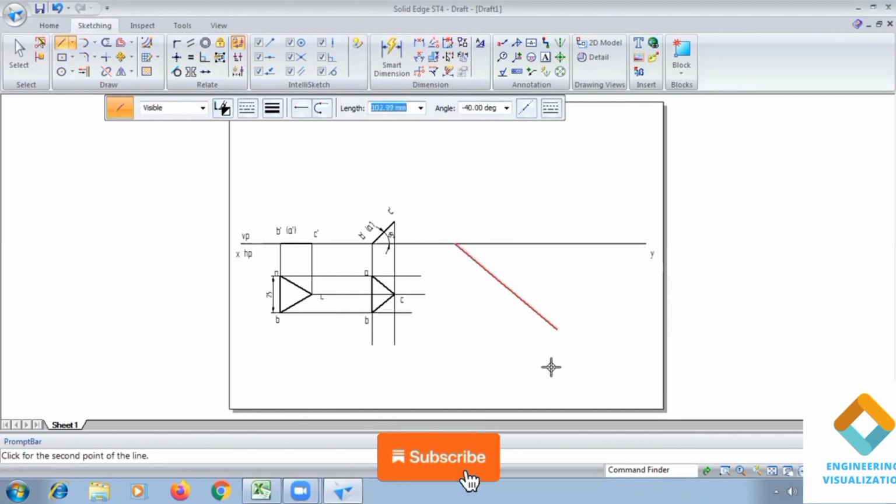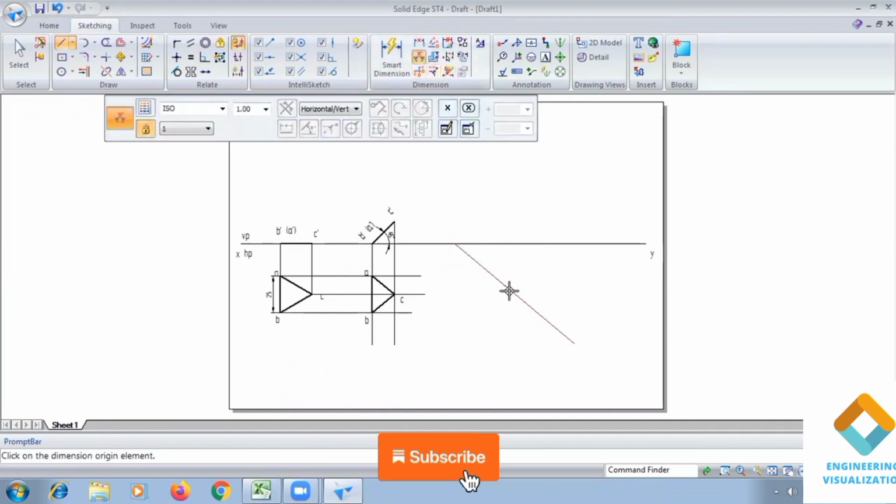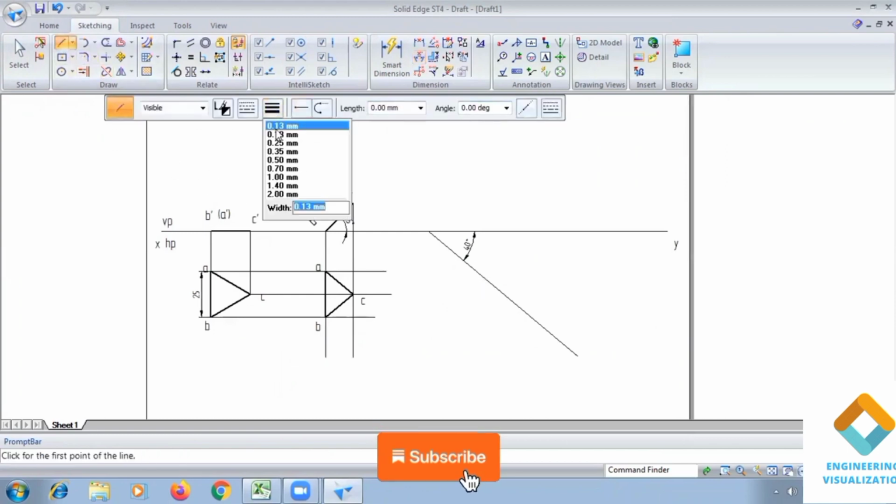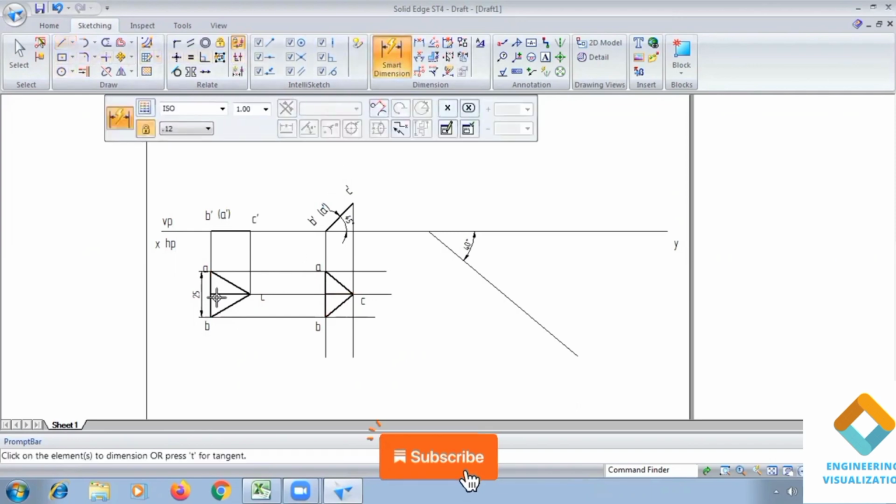Okay, angle of inclination here I'm taking 40, it is 45 given. With respect to that you can take that. Okay, the procedure will be same. Now we need to do the beta angle here. So median we need to draw. Okay, so two medians we need to draw here for the first and second diagram, and we need to measure this length because angle of inclinations we need to do it for the median to find out the beta angle, right?